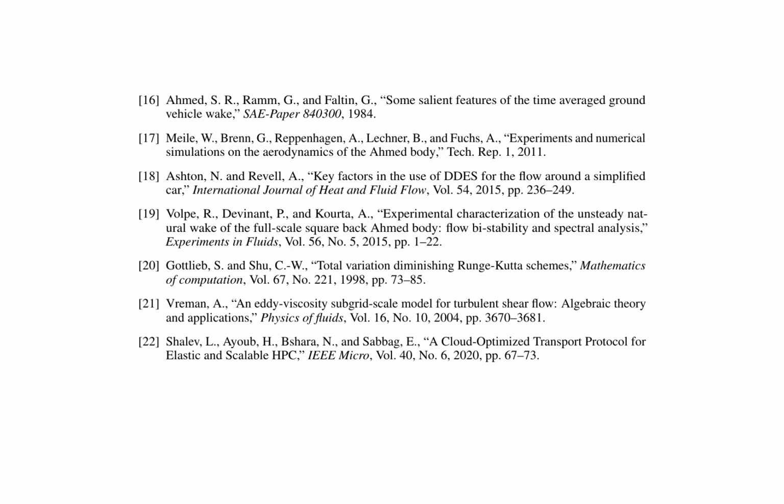Ashton and Revell [18] utilized delayed detached eddy simulation, DDES, for the flow around a simplified car, demonstrating its effectiveness in capturing complex flow phenomena. Volpe et al. [19] experimentally characterized the unsteady natural wake of the full-scale square-back Ahmed body, highlighting flow bistability and spectral analysis. This work underscores the importance of considering unsteady effects in understanding the aerodynamics of vehicles.